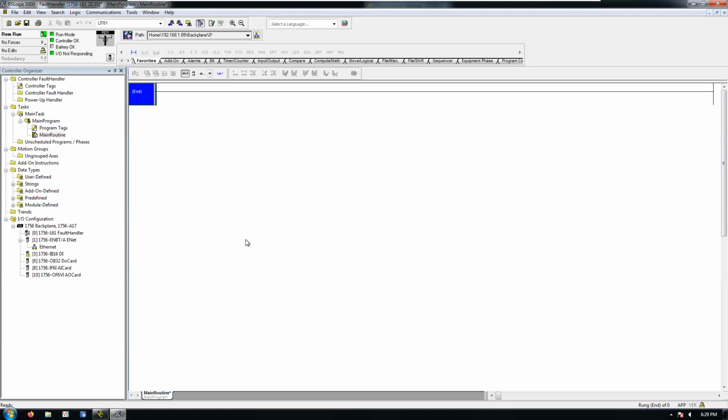Some older controllers can't do it either. If you were doing division inside of a compute block, and you could potentially run the risk of your divisor being equal to exactly 0 at some point, you could just fault the controller randomly. So you'd have to modify your math so that you were never dividing by 0.